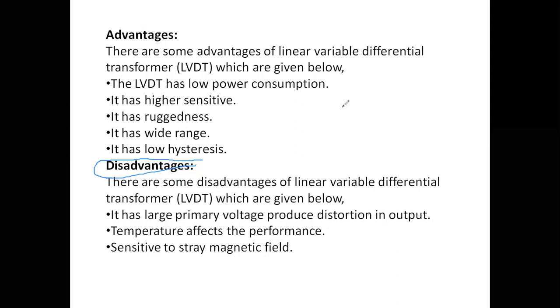If there are any vibrations, then what will happen? Since the core is suspended, the core will tend to vibrate. If the core tends to vibrate, then it will show some output voltage even though the input is zero. So it is the major important problem for me if I use LVDT.